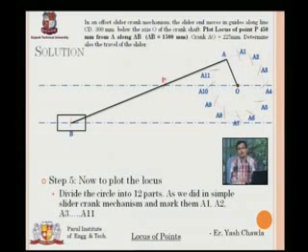Now again I have to mark different positions of the connecting rod, different positions of the slider according to that, and different positions of P according to that. And once I'm done with that, I'll connect the points to get my locus. Here we go.